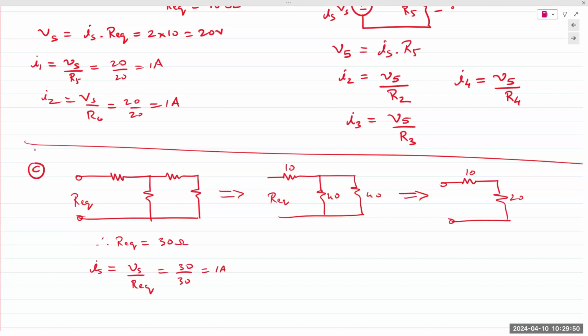And then we expand the circuit back up again in the exact same manner. So if you plug in the voltage source here, the same current Is is flowing through the circuit, which causes a voltage drop similar to example A, plus minus 10 volts and 20 volts.